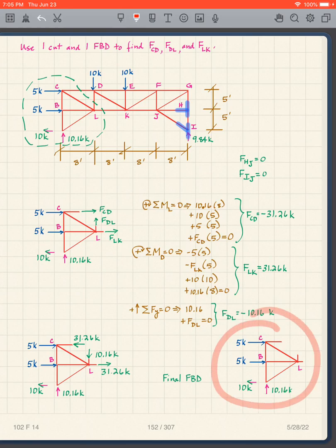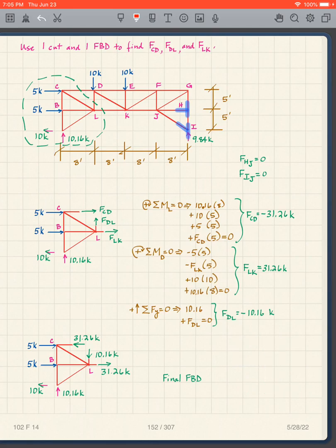I do a copy following this exactly. Copy, paste. Just look down here. That's what I look at, and then I put forces at every location where I made a cut: made a cut there, made a cut there, made a cut there. So I show those forces, and that gives me this. So I now have this free body diagram. I want to find these unknown forces. I can take moments about this point, which eliminates these 2.